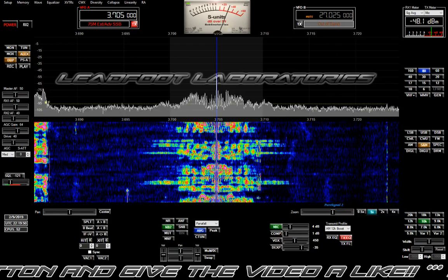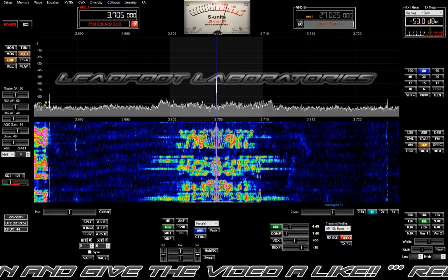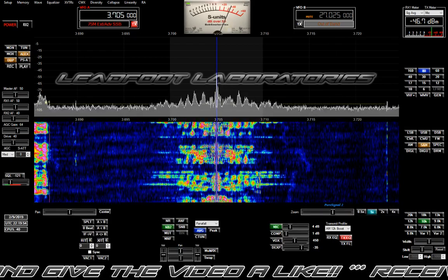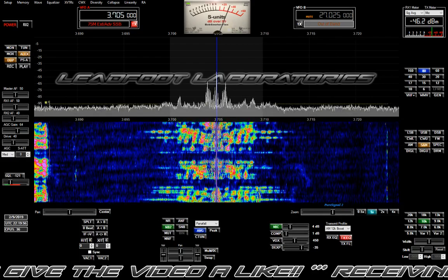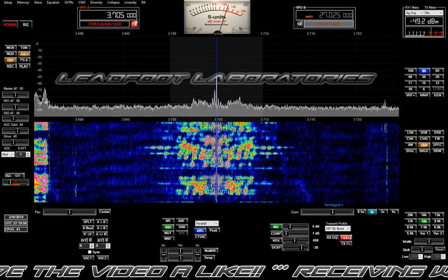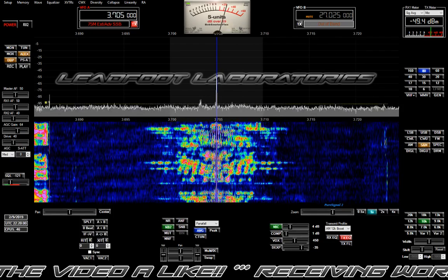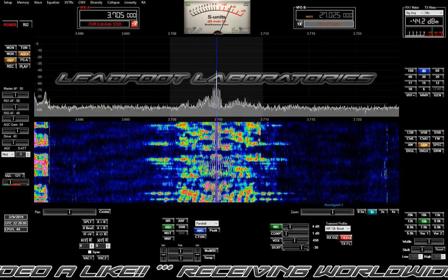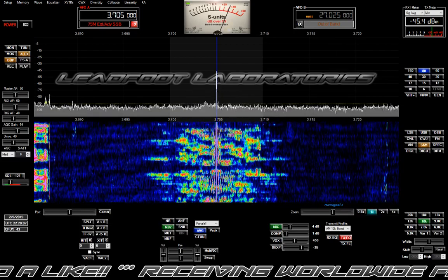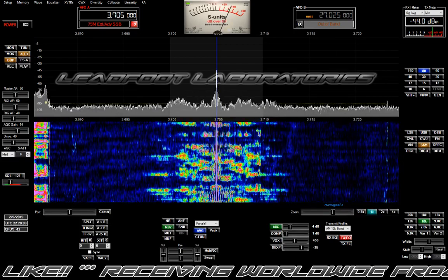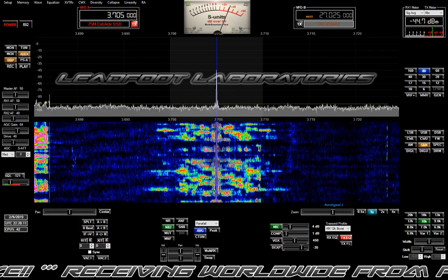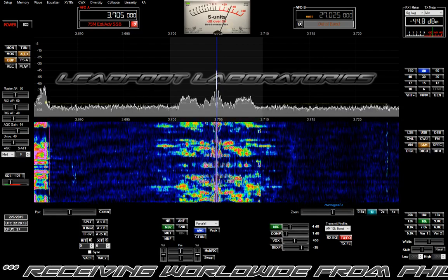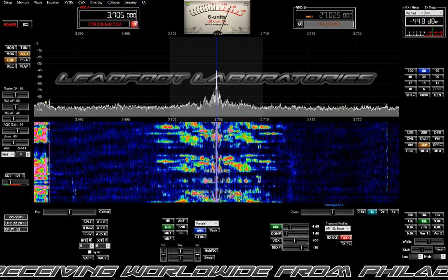And Frank, thank you very much for the comments about what you're seeing on the waterfall. Yeah, that pretty much confirms what I suspected. I'm about 6 dB down at 8 kilohertz, which is exactly where the 8 kilohertz slider is relative to the 6.3 kilohertz slider. It's a 6 dB difference.